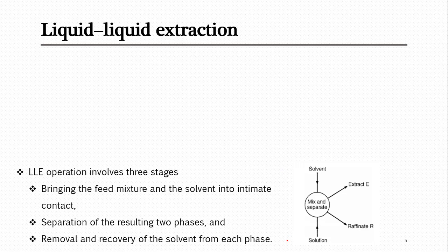The feed here is actually a solution, because it contains more than one component, so he is calling it a solution. You have to bring this solution or feed in contact with the solvent. When they come in contact, they get mixed with each other. You shake them, or mix them by applying centrifugal force or mixing, and after that you give them some time, so they settle into two separate phases.